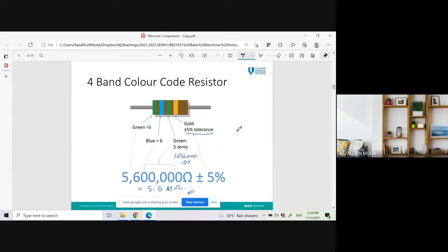So in real case, for our practical, basically, if you have a resistor, you don't need to check the color lah. In lab, we don't calculate the resistance according to the color. We just connect the resistor to the multimeter, and you will get straight away the value of the resistor. Yeah. Okay, that is the easiest way lah in practical.